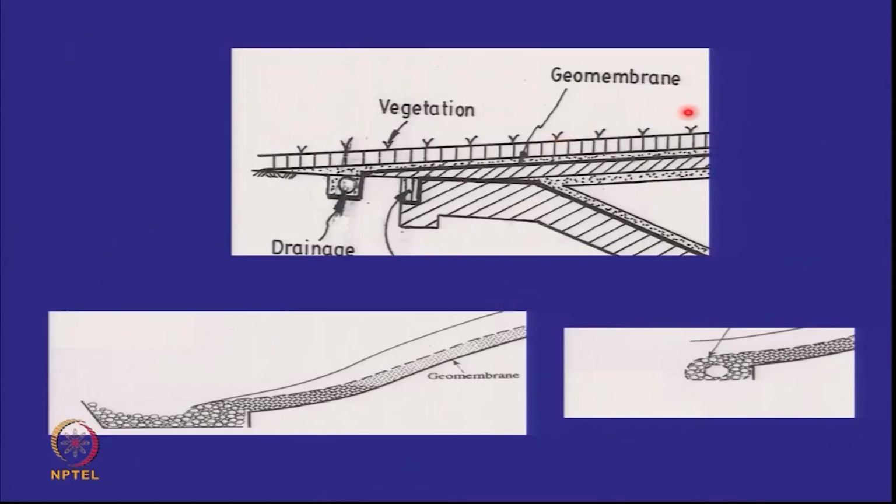So if I look at it, when my water enters into the drainage layer which is above the geomembrane or above the barrier, where does it go? It goes down the slope and it goes into a drainage pipe. Is this leachate? So it's like surface runoff.